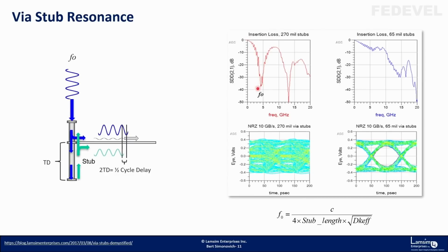So you had a PCB with a 270 mil stub in the via. You had a track, and then you measured properties of this structure. Right. And this is the graph. And does it basically mean that if you have a signal like 8 gigahertz, it would work perfectly fine with this 270 mil stub?